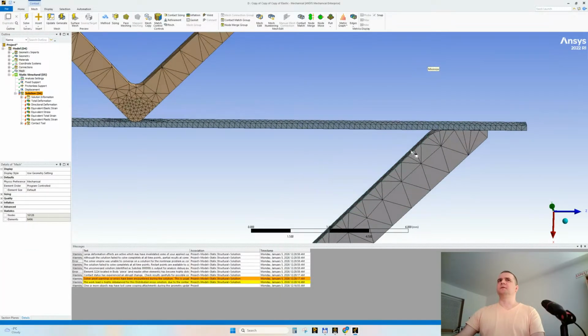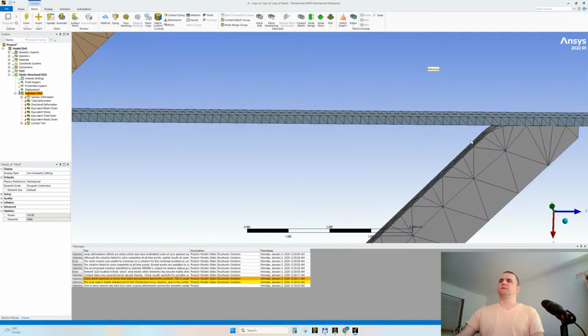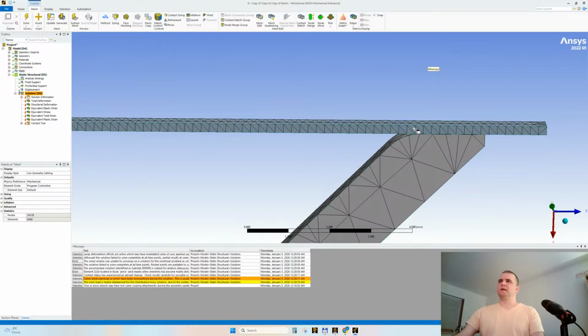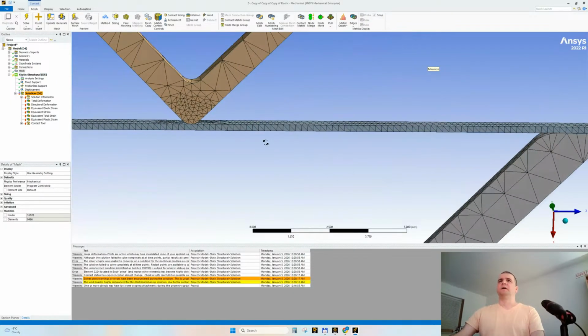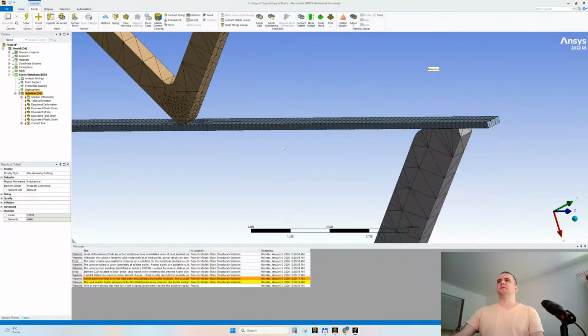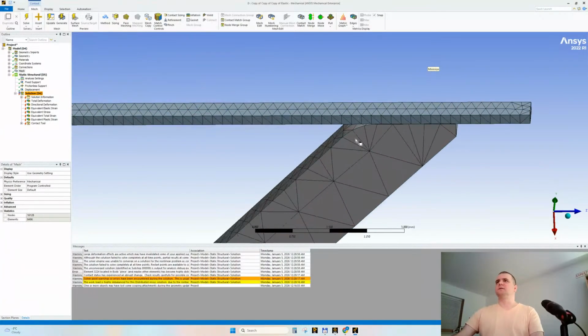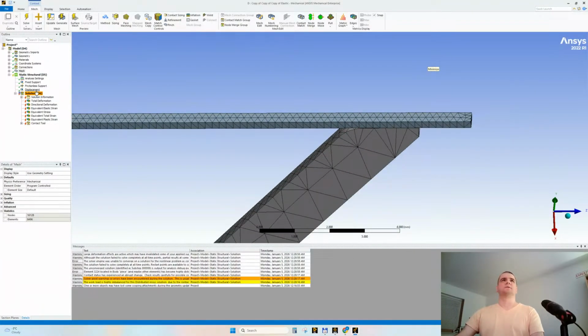This means we need to clearly refine as we did here, yes? We need to refine here, but not only on the surface. We need to refine in depth in this region. A refinement on the surface is almost useless, almost at all times.